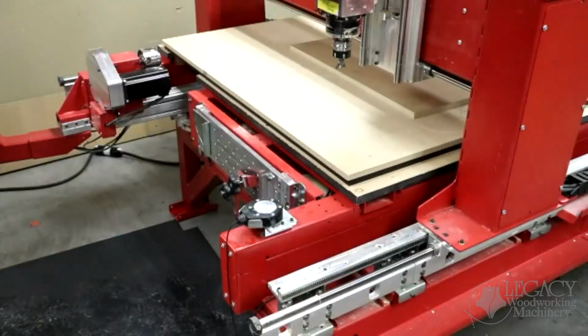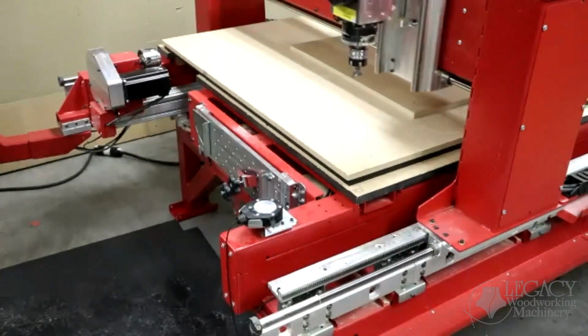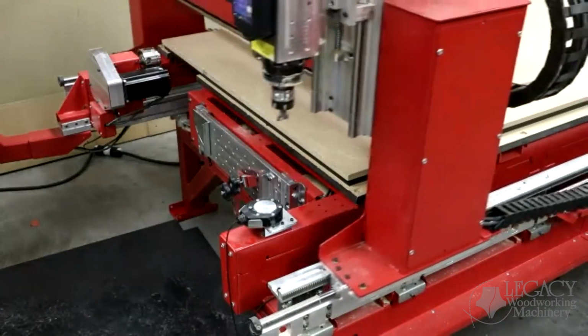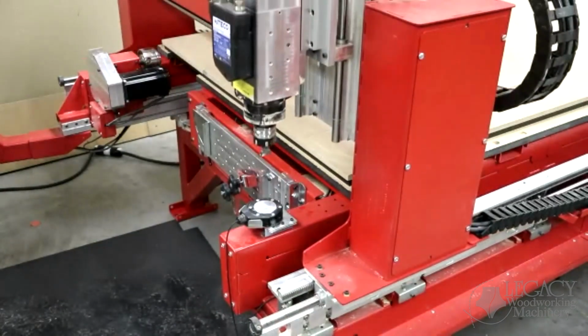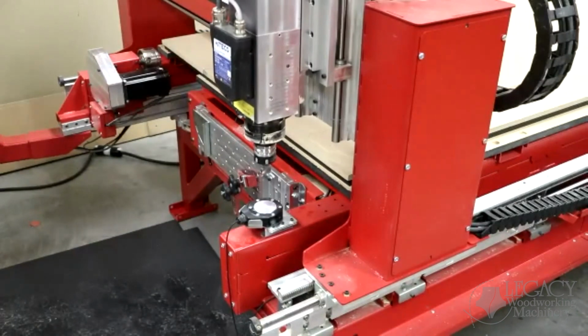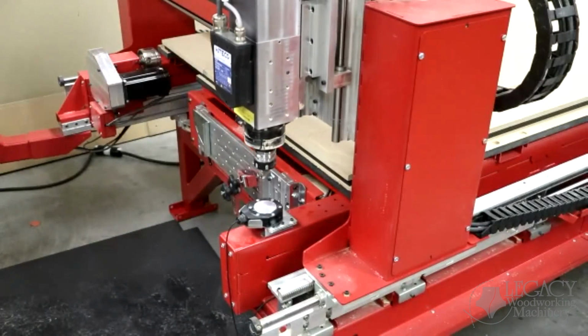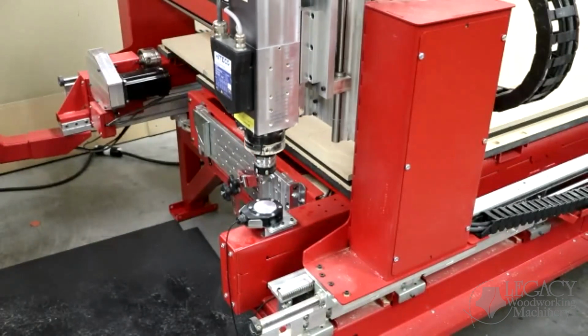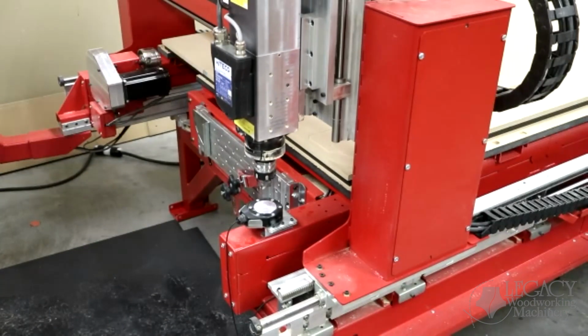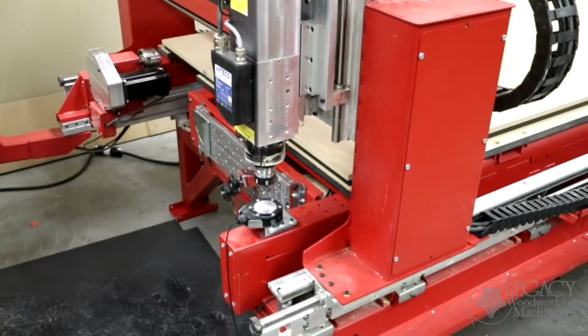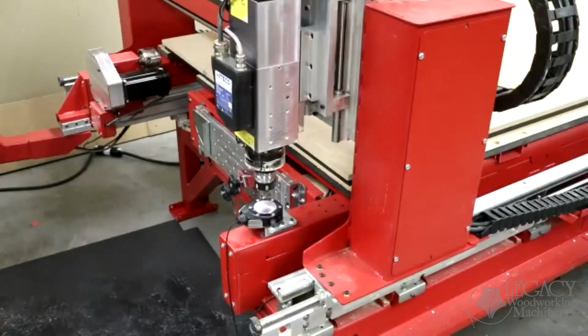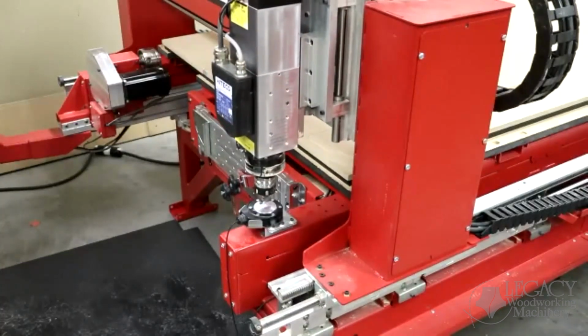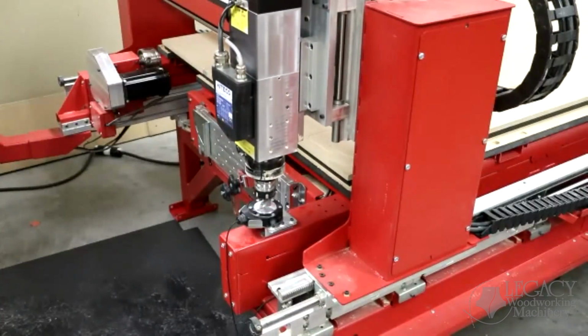Now, when I click on continue, it told me to move the pad, and I click continue. You're going to see it do a rapid Z right when it gets over the pad, right here. And now this has still got quite a bit of distance in here, and we leave it this way because we have customers in here running. If they put a long bit in, we don't want to crash into the Smart Tool pad. So we intentionally leave a pretty good sized gap there, okay?